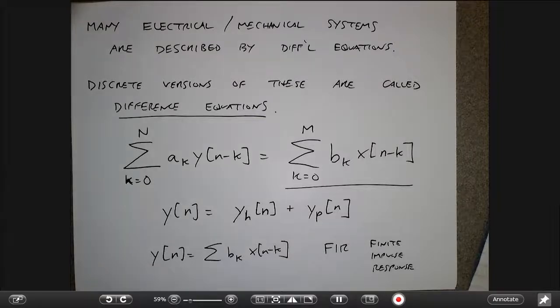Since this is not a class about difference equations, I'm not going to go through this right now. But the mechanisms are the same. And as we're going to see, all the stuff we've been talking about, convolution and the responses of LTI systems, can be greatly simplified with the tools of frequency domain analysis, Fourier transforms and Z transforms. So just generally transform methods, right? When it comes to needing to solve these kinds of things, hopefully at the end of your differential equations class, you found out that the Laplace transform was the best way to solve those equations instead of trying to guess the answer. The same thing is true for difference equations. Once we know the Z transform, life is very easy. So we may come back to talking about difference equations when you know the Z transform.